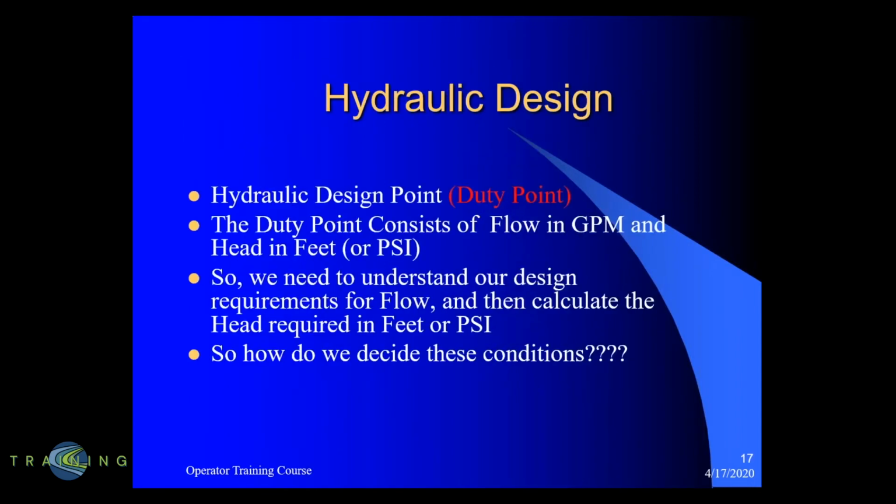So as we talk about pumps, the thing we always do is talk about our hydraulic design point or our duty point. And we're going to talk about how we develop that duty point, what requirements we have to go through to get those duty points, and how we apply them to a pump performance curve. The duty point consists of flow in gallons per minute and head in feet or PSI. So we have to understand as we're designing how we get flow and how we calculate feet.